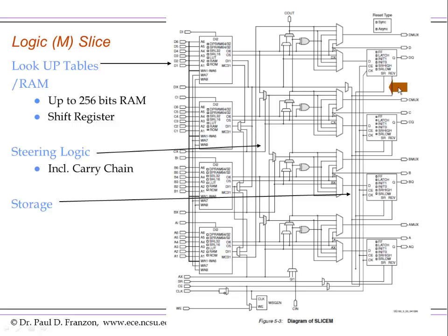They can be configured as flip-flops, latches, and SR flip-flops, that is set-reset flip-flops. What is not shown on this slice, in this diagram, is the overhead to actually program this for specific functions. The idea is that there are SRAM bits that control how these latches or flip-flops, storage elements, are set up.